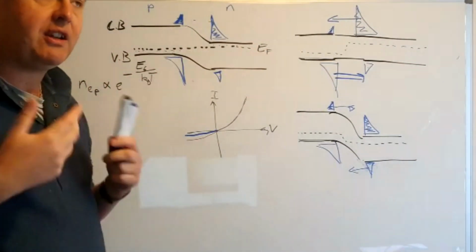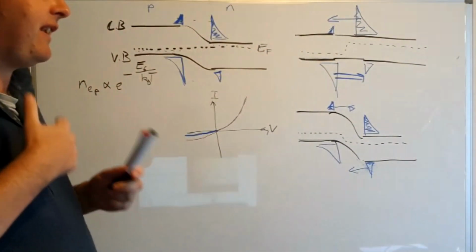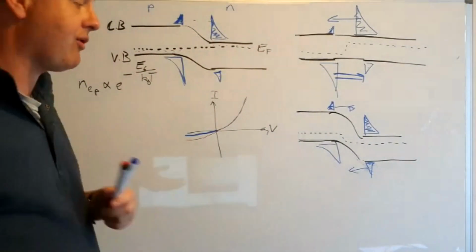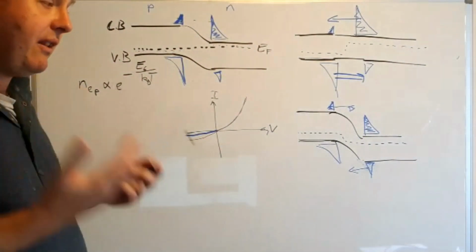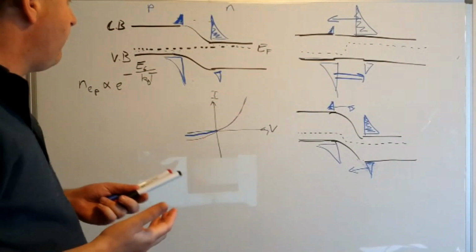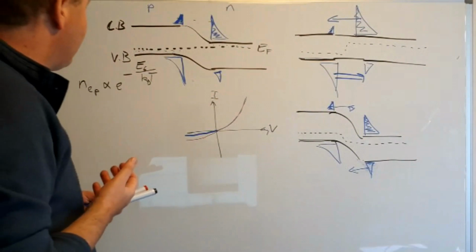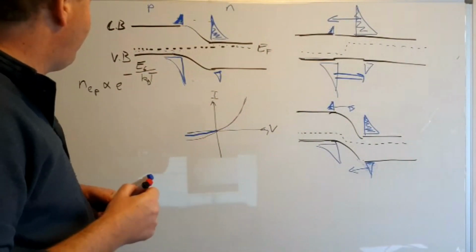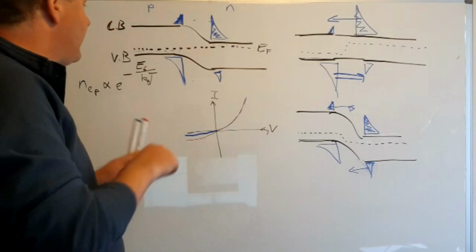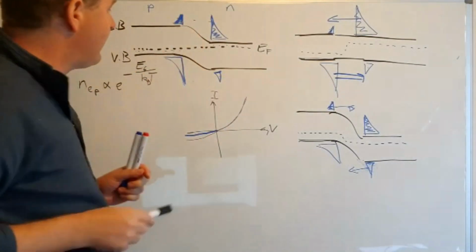So you need to choose the right type of temperature sensor, thinking about more than just how do I measure temperature and how sensitive is it, but the other ways in which it might be affected. The other problem with this sensor is that, okay, it's fine so long as I've got at least some electrons being thermally excited over this energy gap.